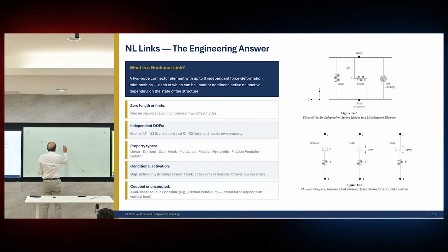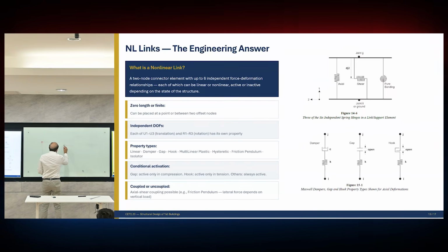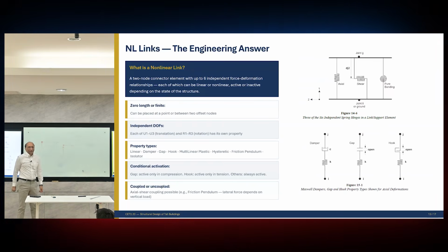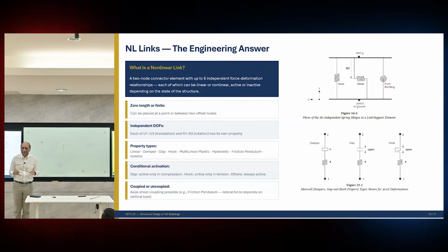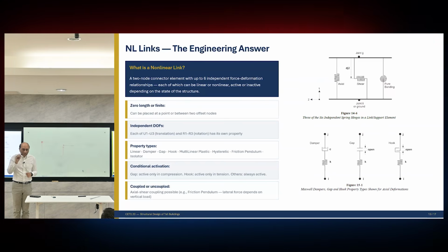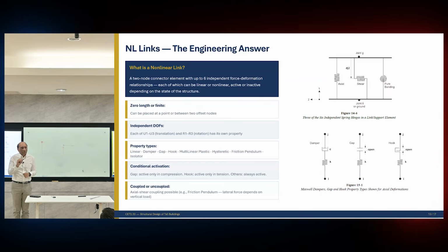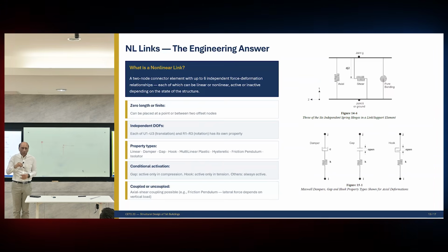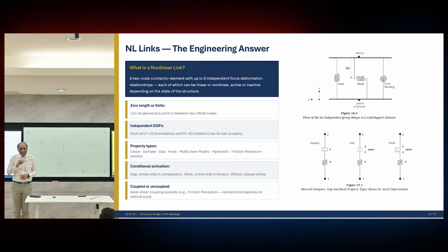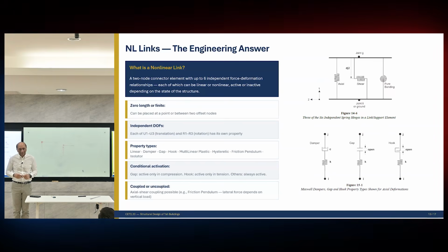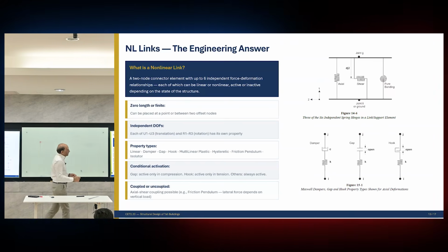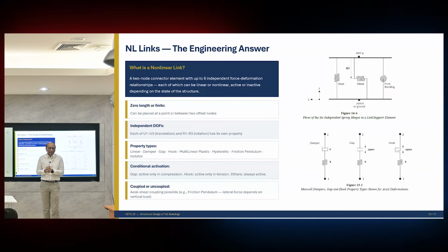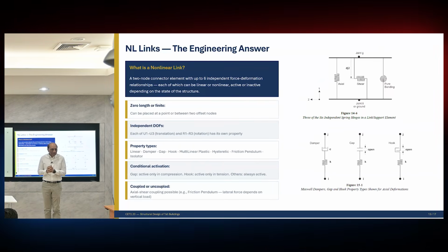What you can do is say, no, I'm going to use 1, and I'm going to use 1, at a very small distance, and I'm now going to reconnect them the way I want. One by one, each of the 6 degrees of freedom, you can disconnect them all and then connect whichever you want and how you want. And that's the power of these links. So you can put one link per degree of freedom, or you can put one link with 6 degrees of freedom together. So it's unlimited.